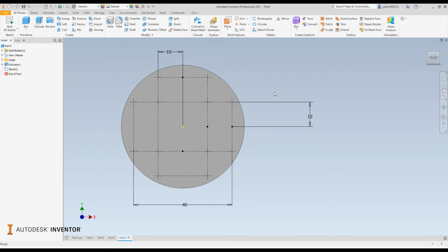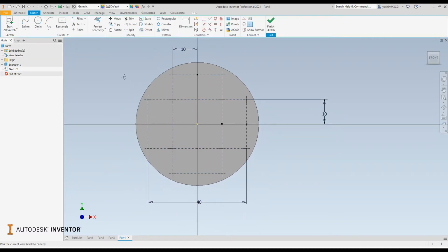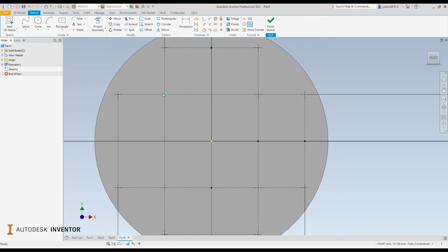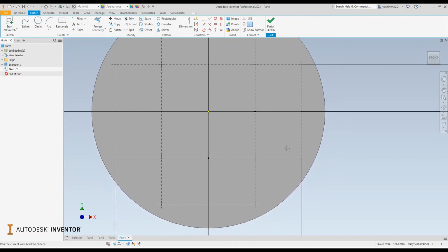So to perform a sketch driven pattern, the first thing you'll need is of course a sketch as well as some points defining the position of certain features. So in this example, what I have already created is a sketch. The sketch contains a couple of rectangles made as construction geometry, and where those rectangles intersect, points have been placed which will determine the position of features. So where they intersect as well as at their ends, standard points have been placed.